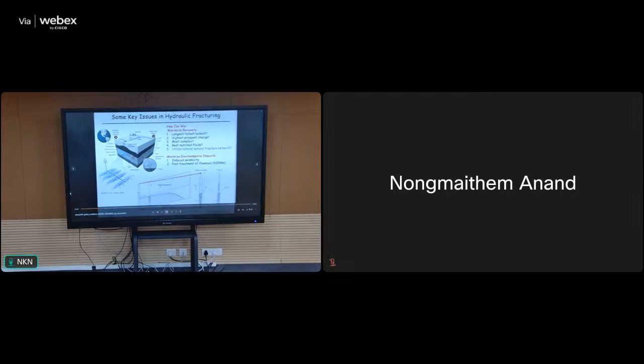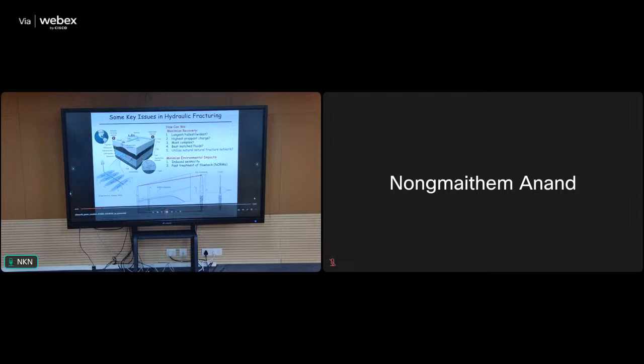So one key question that arises during hydraulic fracturing is, what is the best form of a hydraulic fracture? Is it going to be the longest or tallest or the widest along its length? Is it going to be the one that's accepted the largest proppant charge and therefore is most permeable along that length? Or is it the one that's most complex and reactivates the most natural fractures and is therefore able to reach a larger volume within the reservoir?